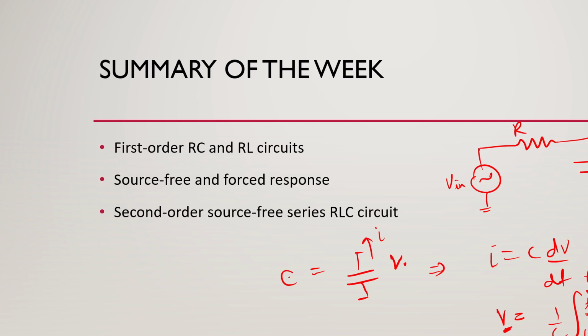That is why you say that this particular element has memory. What is meant by memory? You are remembering the past. So the capacitor also remembers the past. The voltage across it is not only a function of the instantaneous value of current, but also of the previous values of current.